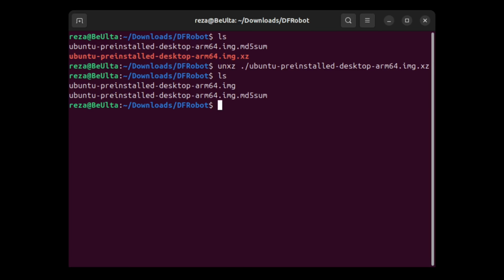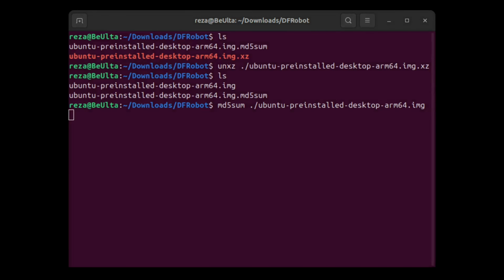And so we'll go and do the checksum on that, which is MD5 and without the image. Again, it'll take a few seconds to perform the checksum through the file. Once that's done, it'll echo the checksum and the file name. Then we'll go ahead and print the checksum that was given to us by DF Robot. So that'll be a validation.